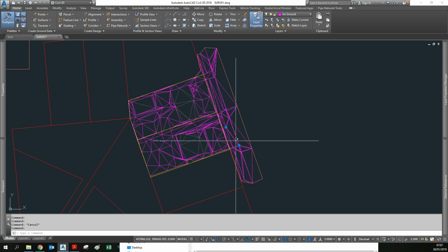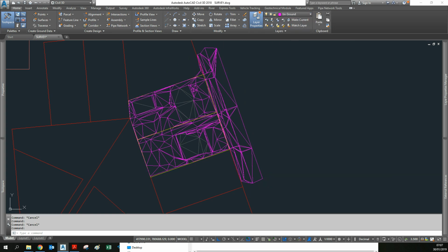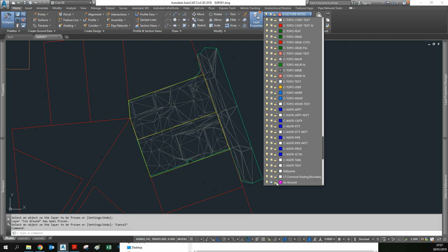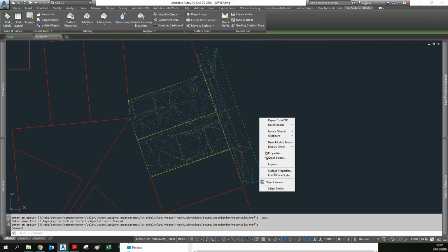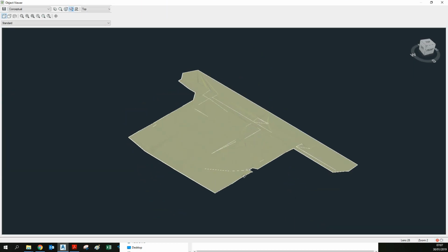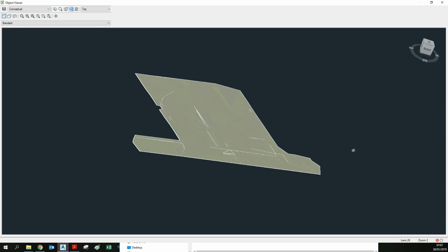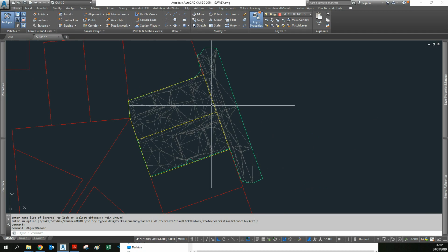And now what we'll see, or we can freeze off, what I like to do is put the border on the same layer as the ground, because you need this border to remain in the drawing, otherwise your surface will change later on. So we can simply freeze it off, and for safety lock it. So now we have set up the survey surface, and the border matches exactly the extent of the survey on site. So that's the end of this lecture, and we're going to carry on with this drawing for the next lecture.